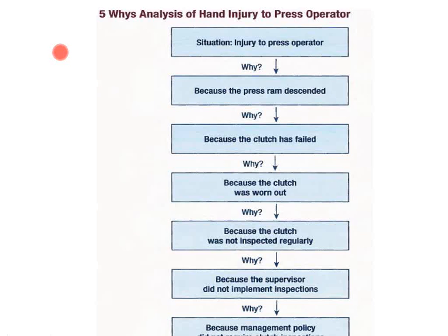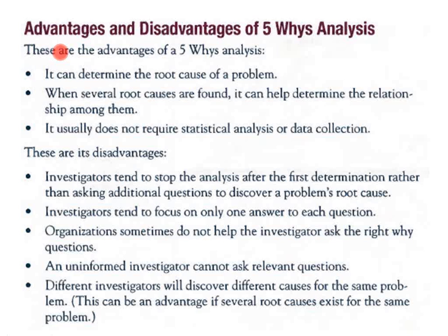So it goes back to when I talk about operations or systems, you might want to say, well, it's because of the maintenance issue. Well, no. There's no process to ensure that we would even look at that. And so now we say, okay, we know in the future that this is a possibility of failure. It's a critical component that can lead to an injury. So therefore, we need to do a preventive maintenance schedule after so many hours that we're going to include now as part of that.